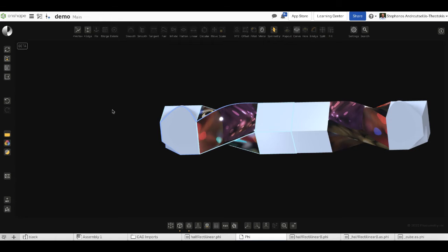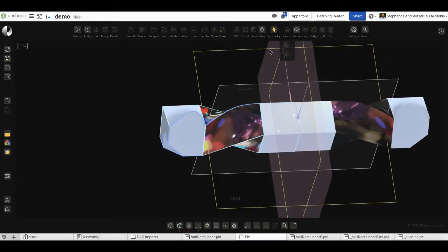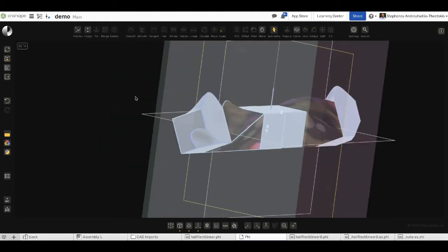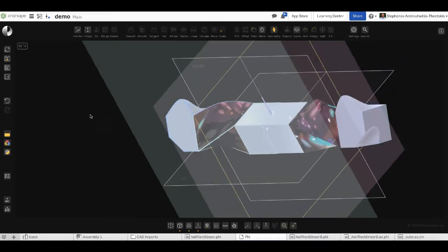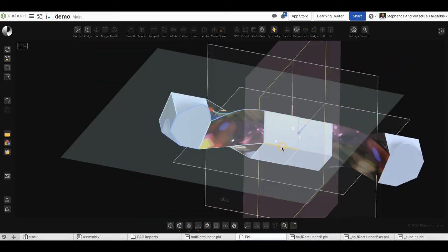And that's mirroring, but we also support a second type of mirroring, let's say, which we call symmetries. So this is a little more detailed in the following sense. Again, I need to define a plane for this. So let me select this plane here. It could be the same as with the mirror or not. And now what I can do is, let's say, surgically, very specifically select certain edges only, and add them into a symmetry set.